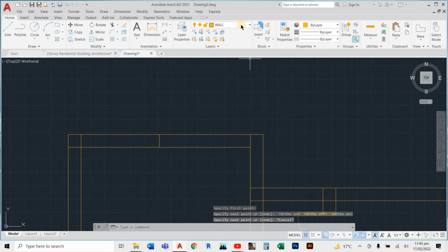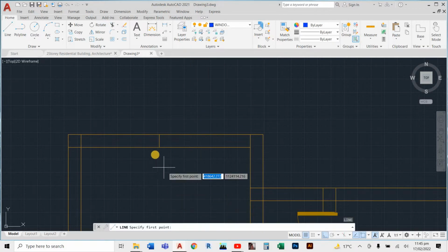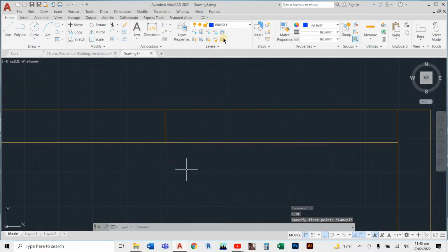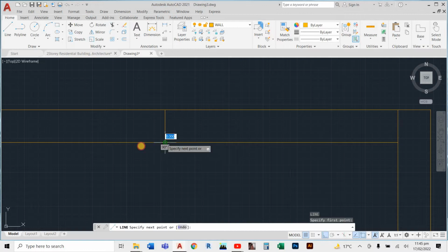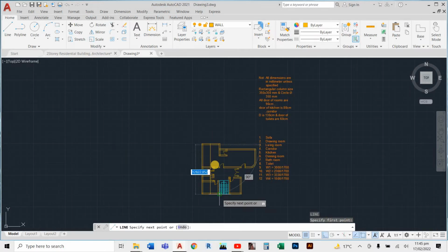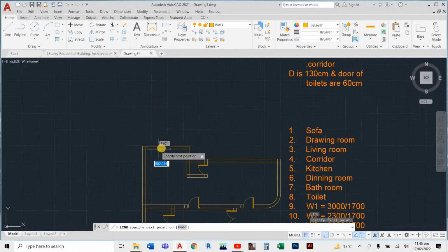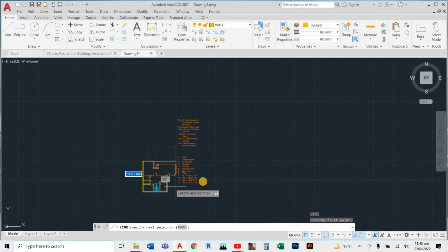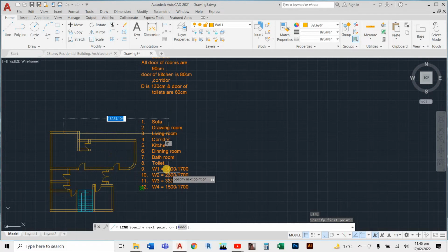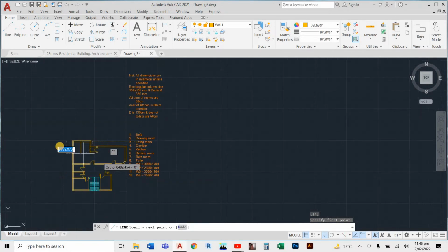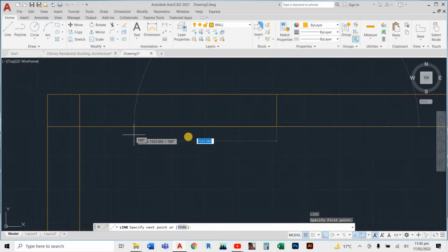We have to go into the layer of the window. In this episode we set all our windows. So 1500 on this side. As I told you in the previous episode, and I'm saying it again, it's not a standard. It's just the details of this project, so that you have a good idea of how you can set the dimension. So 1500.